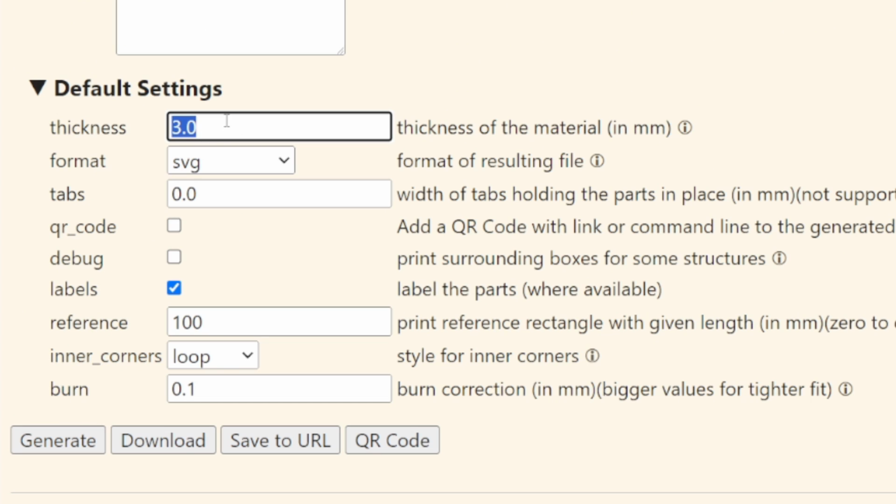Don't take the lumber or the thickness dimensions from the store. Just take a caliper and measure it. Just because something fits into a classification of wood does not mean that's its true thickness. So for example, I have 1/4 inch plywood here that I'll be using for this, but it's not a 1/4 inch. It's more like 1/5 of an inch instead of 1/4. So yeah, just keep that in mind.